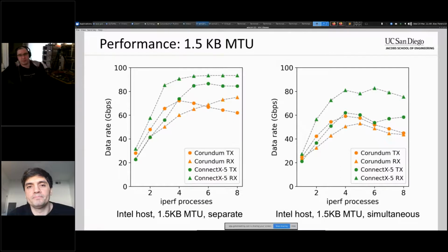Exactly. And perhaps for the benefit of the group, since this is the time synchronization group, maybe you can provide more elaboration on how you do 1588, we support 1588 for TDMA. Right. Okay. So the IEEE 1588 support for Corundum is basically as simple as possible in terms of what you can get on a NIC. So we have a hardware clock with, I think, 32 bits of fractional nanosecond resolution, so you can very precisely adjust the frequency it's running at from the host.